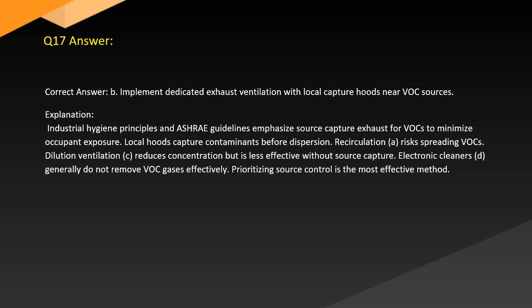Answer. Correct answer B. Implement dedicated exhaust ventilation with local capture hoods near VOC sources. Explanation. Industrial hygiene principles and ASHRAE guidelines emphasize source capture exhaust for VOCs to minimize occupant exposure. Local hoods capture contaminants before dispersion.